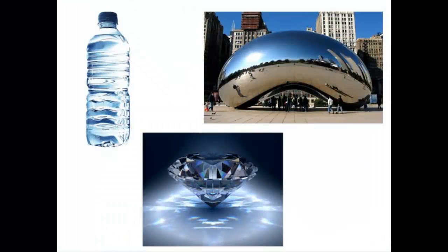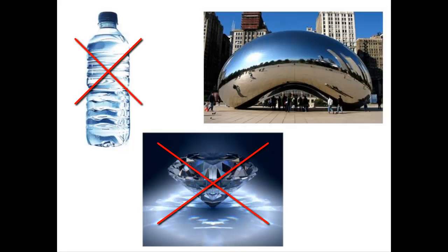It is important to note that not every object is suitable to be produced using 123D Catch. I will now run through some objects that may prove troublesome. Transparent, reflective or shiny objects, such as a water bottle or a glass object, will not work well. The problem with these types of objects is that the appearance of the object changes as the position of the camera moves. The change of appearance makes it more difficult for 123D Catch to find common points in different photographs and stitch them together. 123D Catch works by looking at every photo and locating common points in each. So when light is reflected differently on shiny objects, it changes its appearance and causes distortions on the finished 3D model.